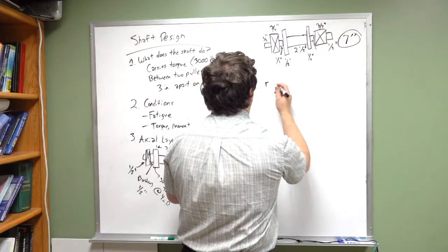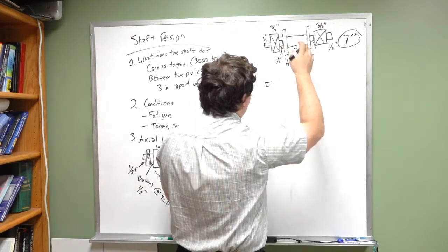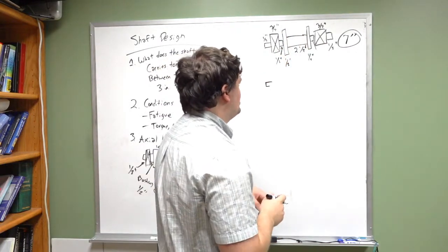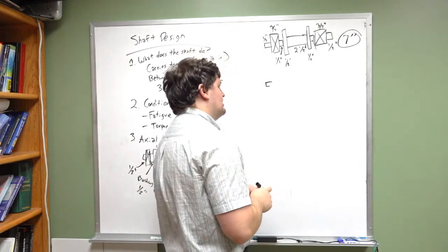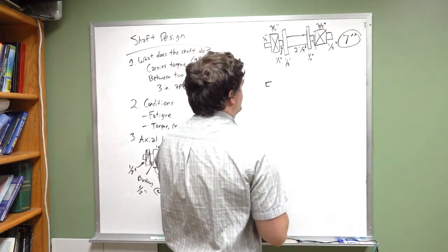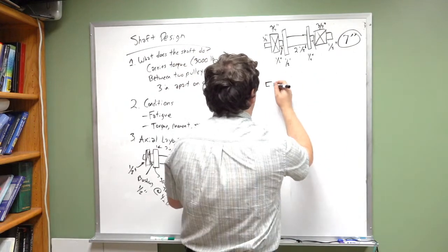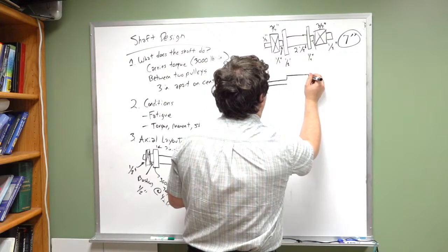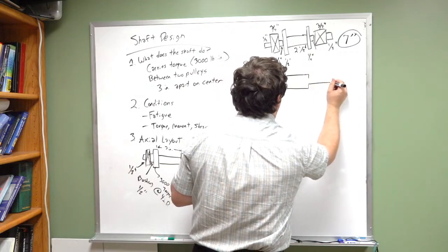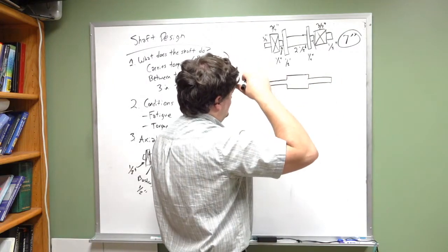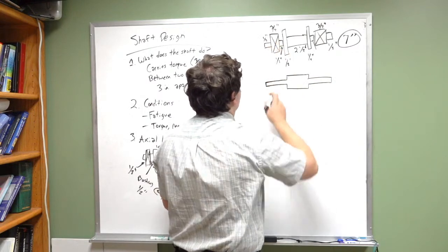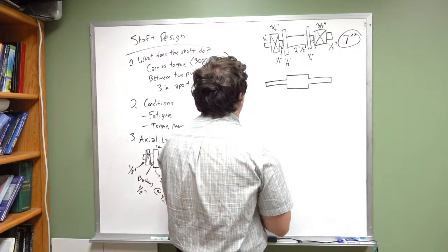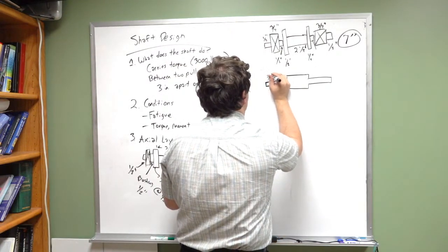Okay, so just drawing this, I'm going to go ahead and remove the bushing. I'm going to replace the bearing with a load. I'm going to replace the pulley with a load, both of the pulleys, and also the other bearing. So I've got this, goes up, you've got a step shaft in the middle, like this, and that's 7 inches, okay? And we know that 1 inch and 3/8 of an inch, that's 7/8 of an inch from the end. We have